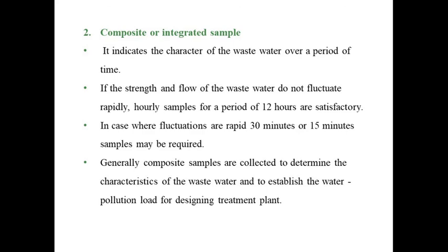Acids, that is sulfuric acid, nitric acid and organic acid. Alkalis in the form of lime and sodium hydroxide. Then toxic matter, which is toxic to man, animals, plants, fish and microorganisms, like heavy metals, pesticides, ammonia, color and volatile matter. These are all ingredients in sewage, wastewater and industrial wastewater.